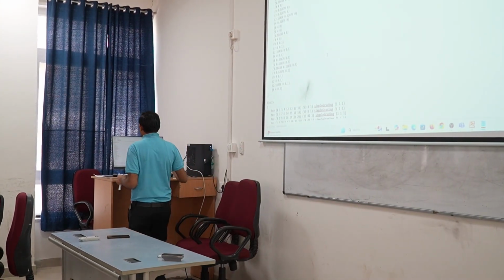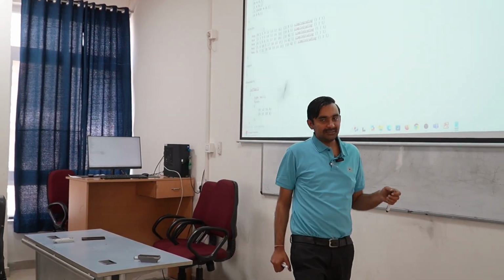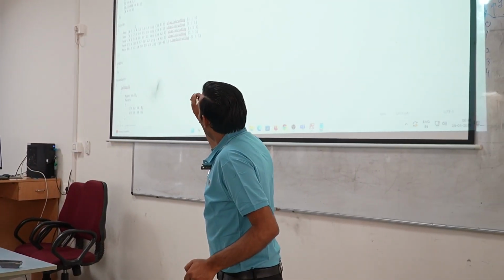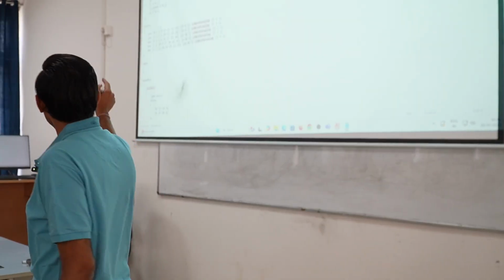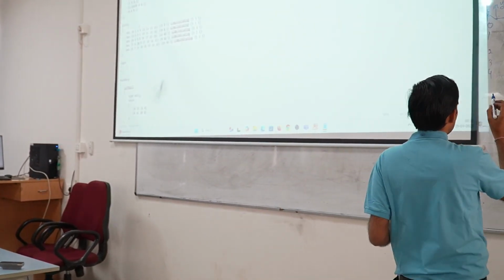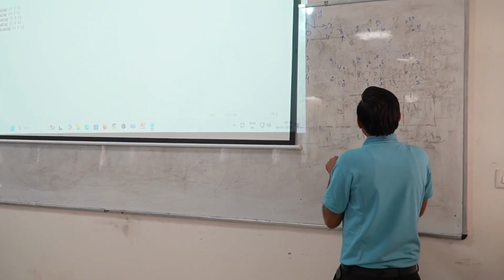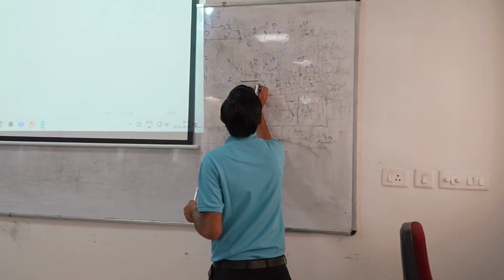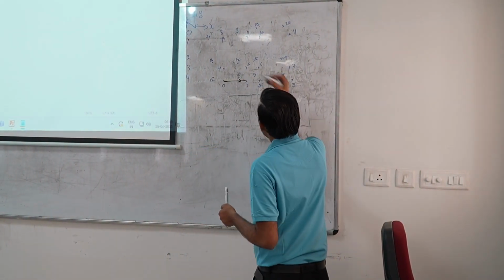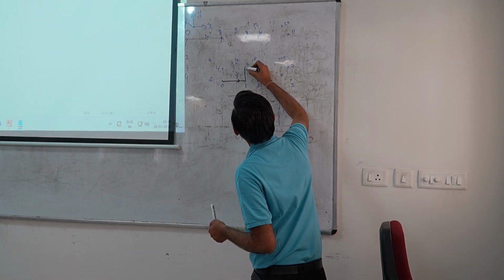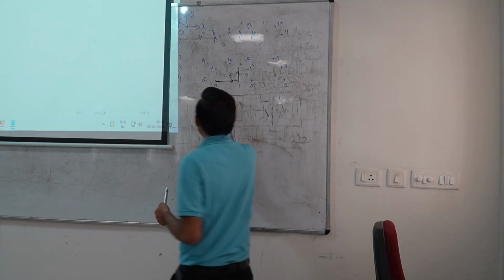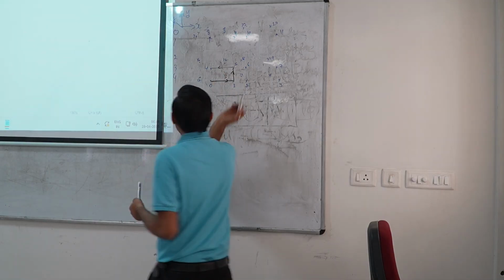After we define all the vertices, the next part is blocks. What do we define in blocks? First hex. How many points does the first hex contain? 0, 1, 5, 4. Let me join from 0 to 1, then it is joining 5, then it is joining 4.